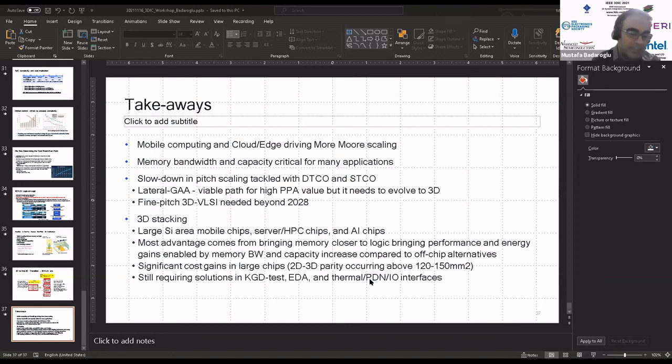It's a big challenge, and the 2D channel material growth is a big problem. In fact, any irregularity there immediately translates into performance, and also how to make a contact to 2D material is a challenge. So these are two challenges, like a substrate and the contact technology.